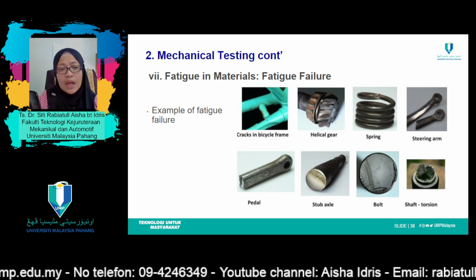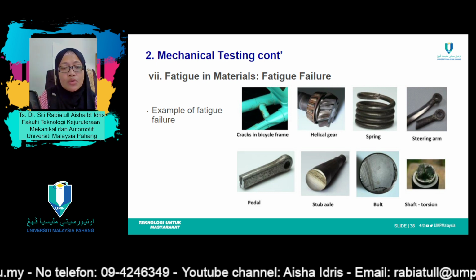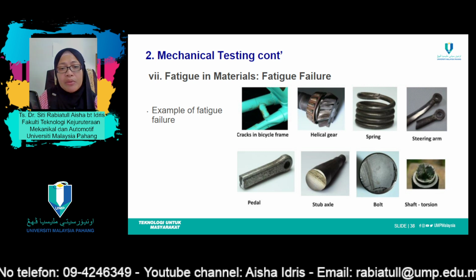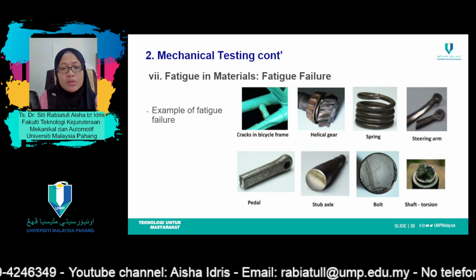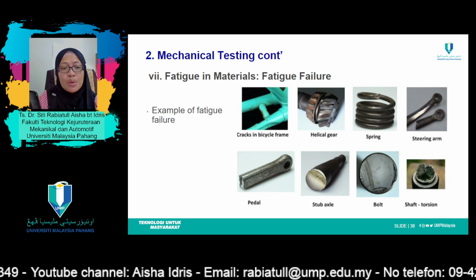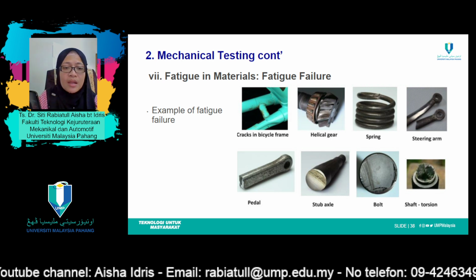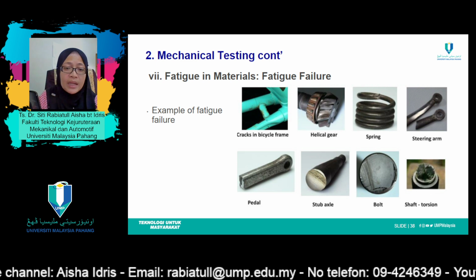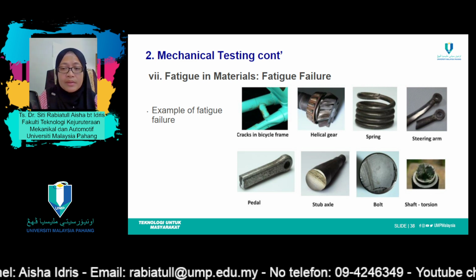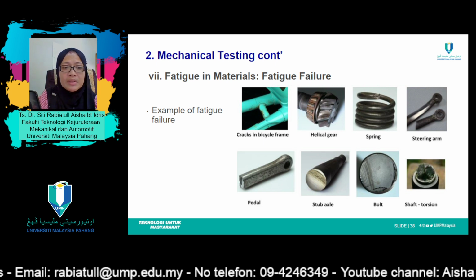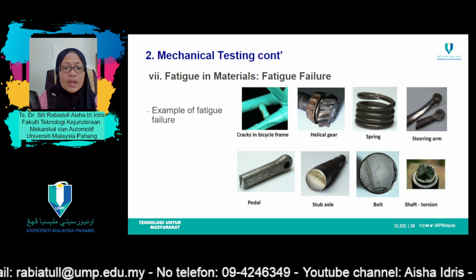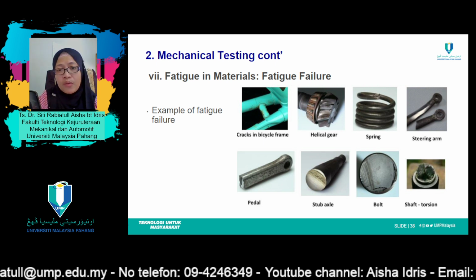The fatigue life of a material is the total number of cycles that a material can be subjected to under a single loading scheme. It is also used to determine the maximum load that a sample can withstand for a specific number of cycles. All of these characteristics are extremely important in any industry where a material is subjected to fluctuating instead of constant forces.